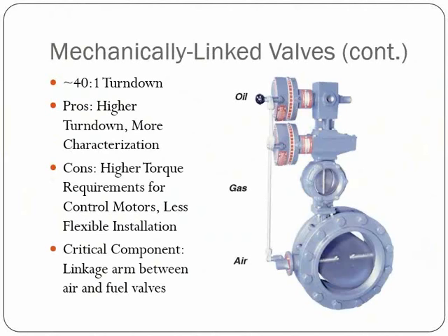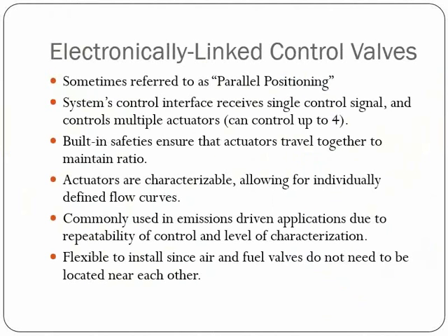Moving forward with the electronically linked control valves, you now have full characterization over that air valve, so that you're not just setting low fire and high fire and doing a linear ramp between the two. If the application calls for it and you want to get additional characterization out of your air valve, these electronically linked control valve products will give you that characterization.